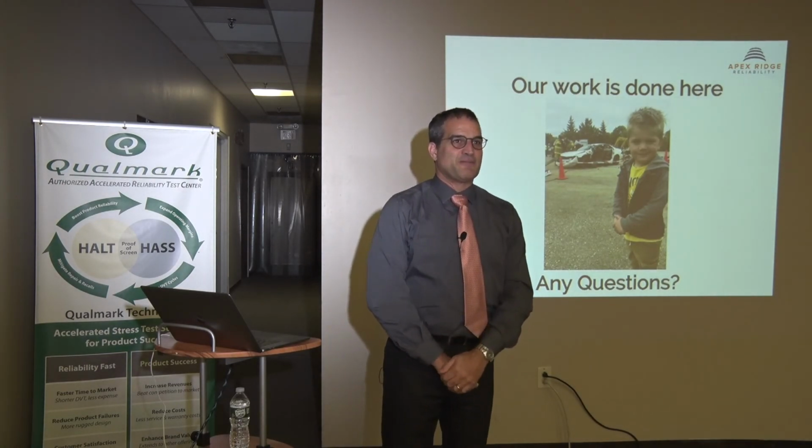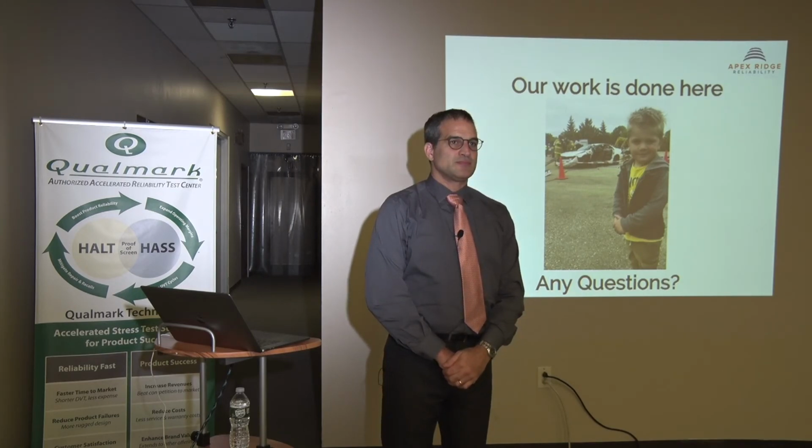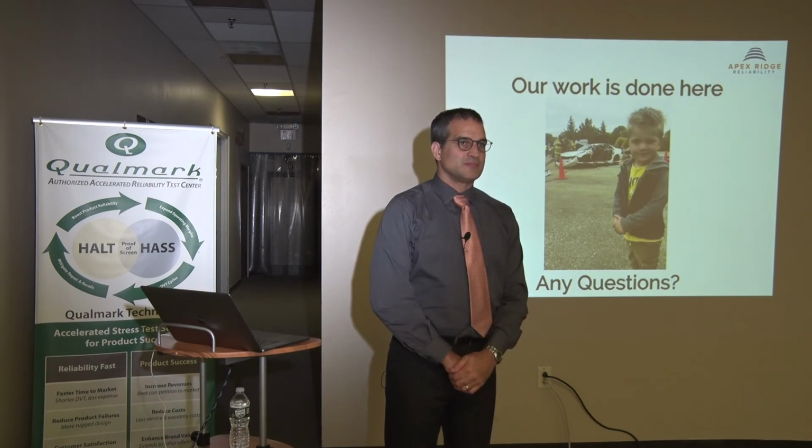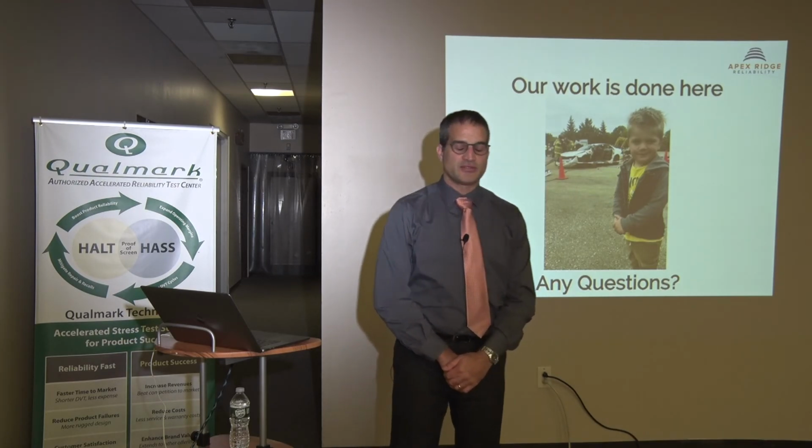I see a question back there. Yeah, just in context of basically the FMEA coming up with the RPN and things like that, I'm wondering basically how do sample sizes come into play here in terms of evaluating, right? I mean, you've got to have a certain confidence level on the outcomes. So I was wondering if you could basically address sample sizes, and then also if you might be able to make a few comments about Weibull statistics in the whole issue here concerning HALT testing. Sure, yeah, that's great.